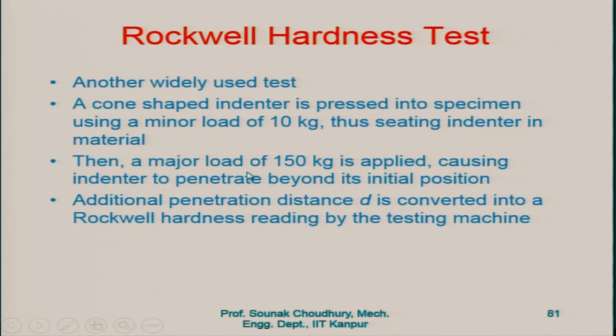Then a major load of 150 kilogram is applied. First we put the minor load so that there is a small indentation and the indenter sits in the material, and then a major load of 150 kilogram is applied on the same indenter, causing it to penetrate beyond its initial value.